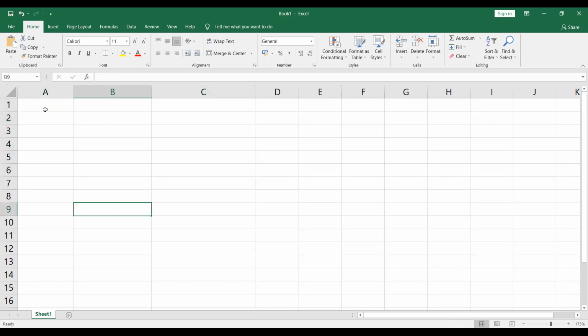What I need to do now, the next step after you get the column reinforcement, whatever values you are getting, is to find how much reinforcement you are going to provide for that particular column size. So how you are going to find it out is by the method that I'll explain to you. First point is type in MS Excel size of bar, that is the reinforcement bar.